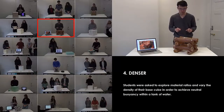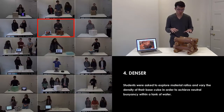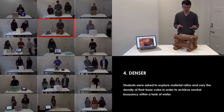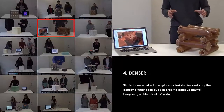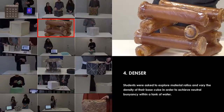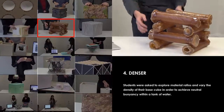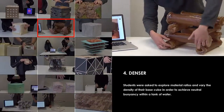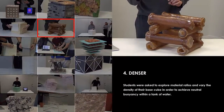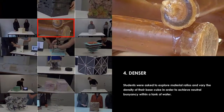Our second cube is denser, and we borrowed the idea of submarines. We know that the glass bag density is 1.1 while the water density is 1, so we need to mix different densities together to make this thing float in the water. If we make it solid, it will definitely sink, so we make it hollow. These two tubes are hollow while we seal the other tubes, and we leave a little hole there so we can control the volume of water that gets into it. So we can control the heaviness of the whole tube.